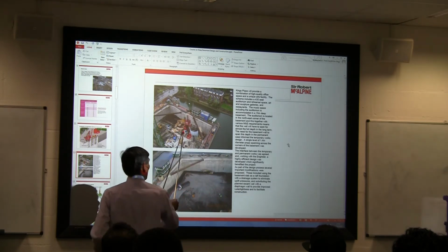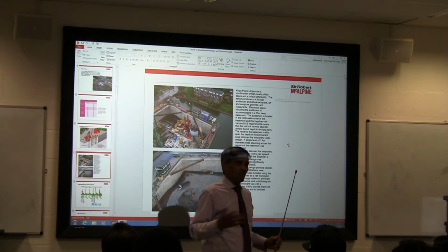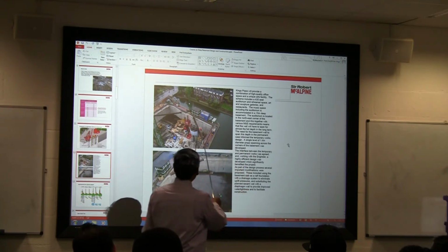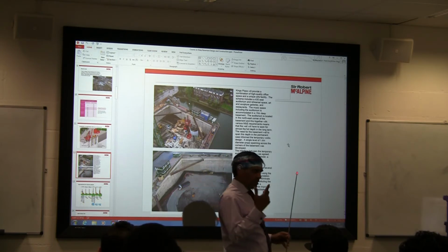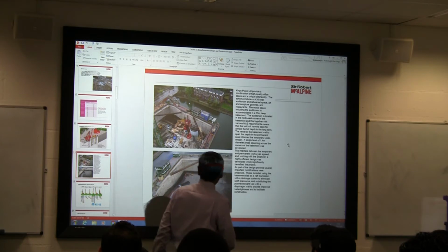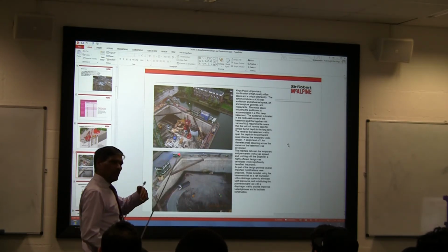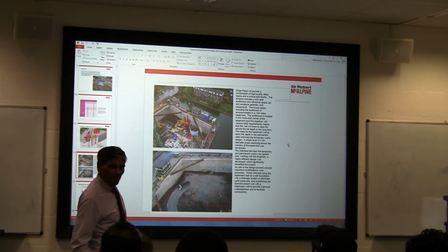So I need space. It sanitizes the space. It's occupying a lot of space. I can't do anything else until I finish all that and remove the bentonite plant. This is what I'm saying. You have to think about those logistics also. What are we putting on site? So that's the diaphragm wall we have done. You can see clearly how best interlock can be achieved even when you are working next door to water.